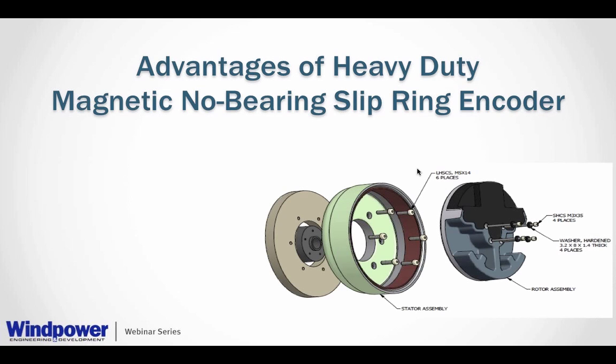A lot of low-cost encoders don't use regulators like they should. Ask your encoder vendor, are you using voltage regulators around the entire encoder? You'll need an automotive grade quality because you're seeing surges on the line. You're going to see induced voltages that aren't from the encoder. They're from the drive or other things, and they're going to kill your encoder, or for lightning, from that matter.